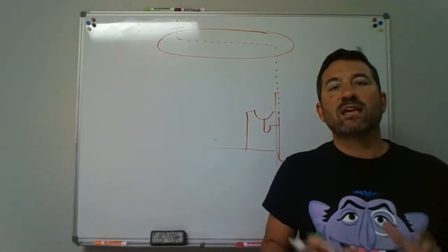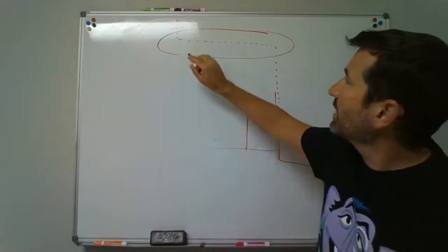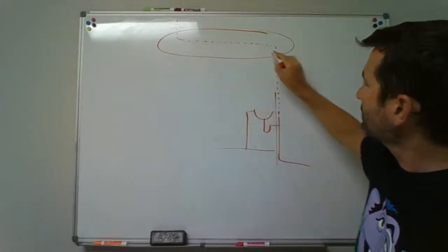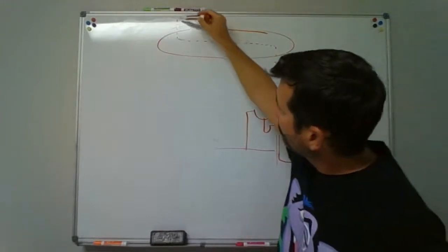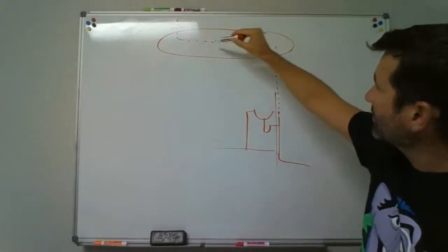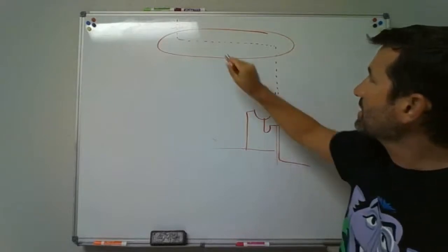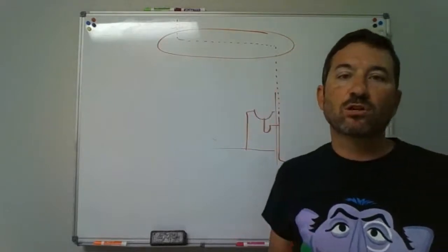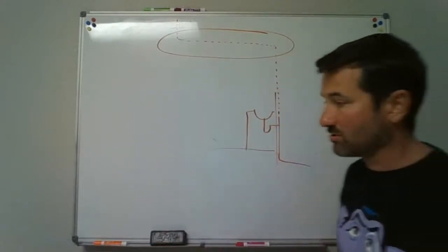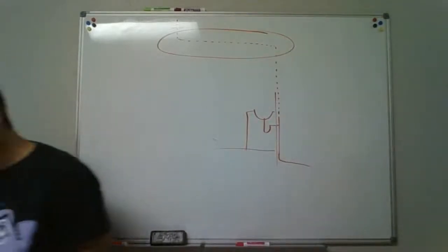All it has to do is have positive slope, or be pitched in such a way that it slopes back towards the fixture it serves. So maybe if it rains and we get a little water down this pipe, it's going to drain down this vent pipe and just run down the drain. So yes, all you need is positive slope, pitched back towards the fixture it serves. Okay, that's grade on the pipe.